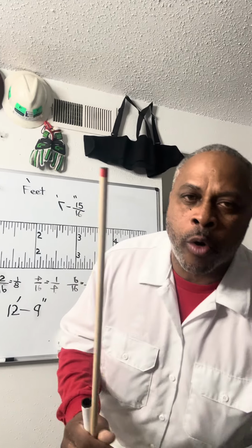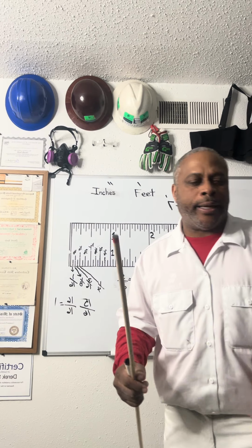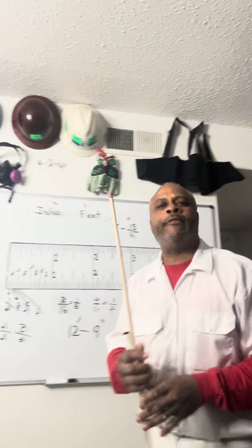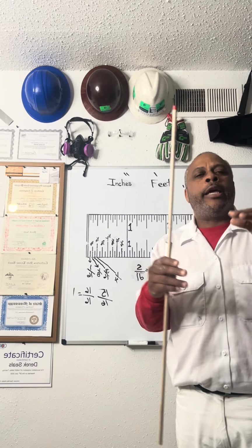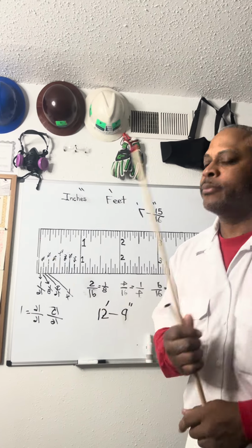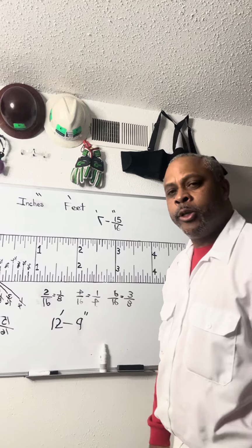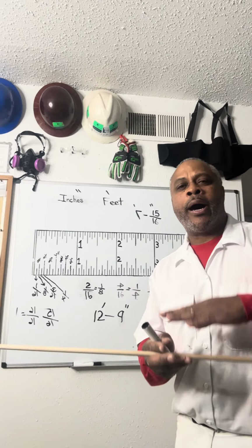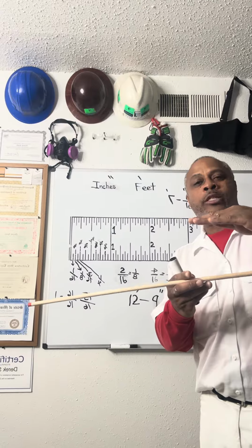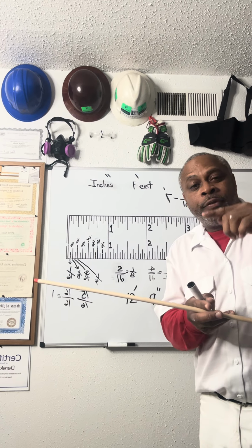You're going to have to pull this out all day long and read it. And you're going to have to mark it and be very accurate because it can determine the height of your wall. If your wall is too high, Lord have mercy. You mean to tell me, man, I told you what the measurement was. Because you're adding a bottom plate and 2 plates on top. One is called a top plate, one is called a double top plate. That stud fits in between.